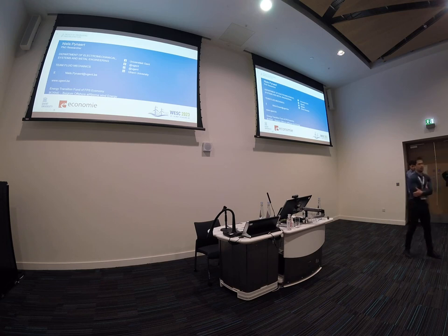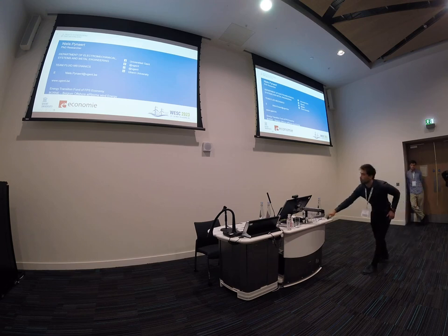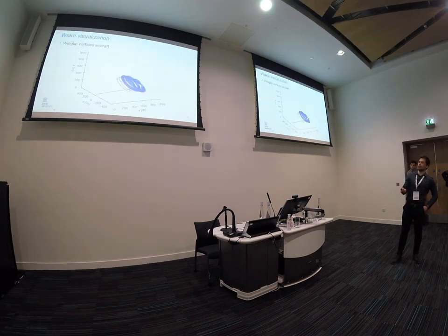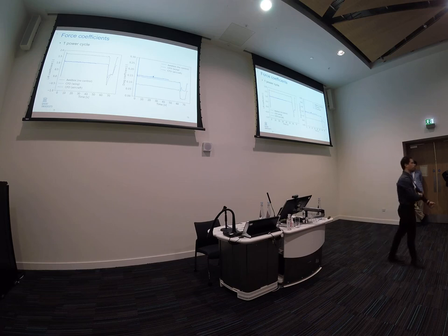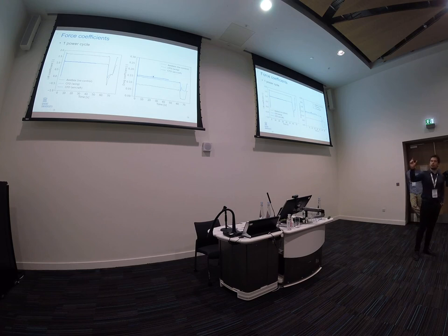So yeah, it's indeed quite expensive. To put a bit of numbers, the framework I showed here uses a mesh of around 20 million cells. And if I go back to the power slide, or the forces, to do one loop, this was done on a supercomputer with a bit more than 1,000 CPU cores. And one loop took 3 days on the supercomputer for the wing, and that was then able to do a full loop. But again, these 3 days were not enough to do the CFD for the full aircraft. So there I would need more than 3 days. Based on the profile, I would say 6 days.